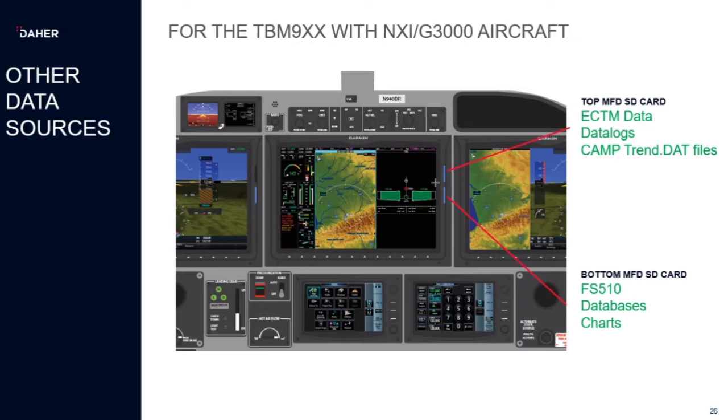Fortunately, from aircraft 1216 forward, you do not have to worry about sending trend data, as it is done automatically by the Fastbox. While the system still records data log files, which contain various engine parameters and flight information, this and much more is also recorded by the Fastbox. Exceedance data is stored in the display's internal memory. Once we have received the data, we are then able to apply the tools we have developed.